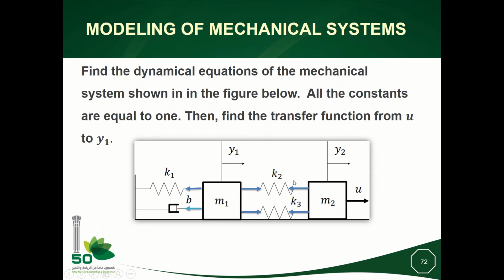So this is a system with 2 degrees of freedom. It has two displacements: M1 has a displacement Y1, and M2 has an independent displacement Y2. So the number of degrees of freedom of this system is equal to 2. So we will have two differential equations that are coupled with each other, linear with respect to the variables Y1, Y2, and the respective higher derivatives. I will start first by writing Newton's law for the mass M1.